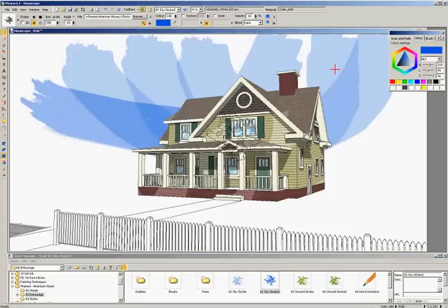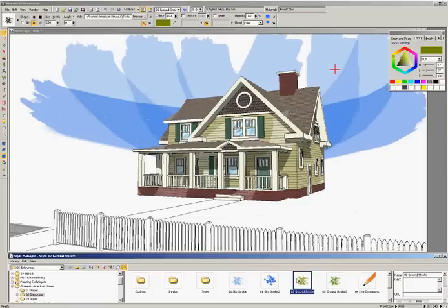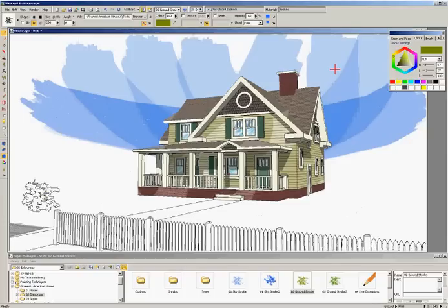One important thing to say actually when you're exporting out of SketchUp is to remember to tick the option to include the ground plane as well, otherwise you get some rather interesting effects. But it's a simple tick box on the export, so I promise you that you won't forget to do it more than once. So click and hold and just swoosh, and I'm just literally going to whiz that across.